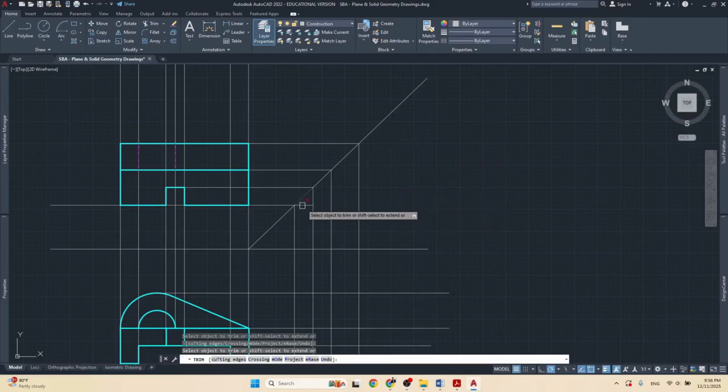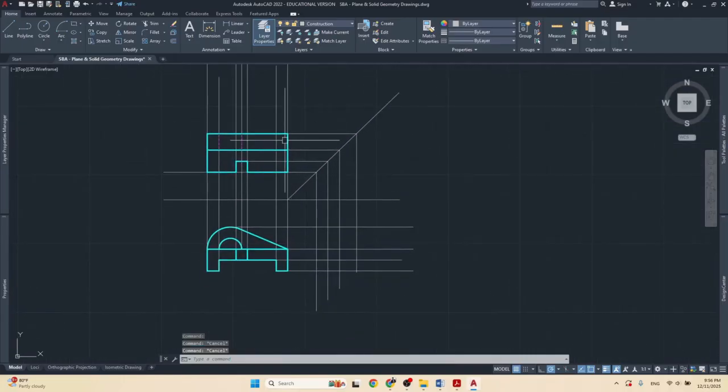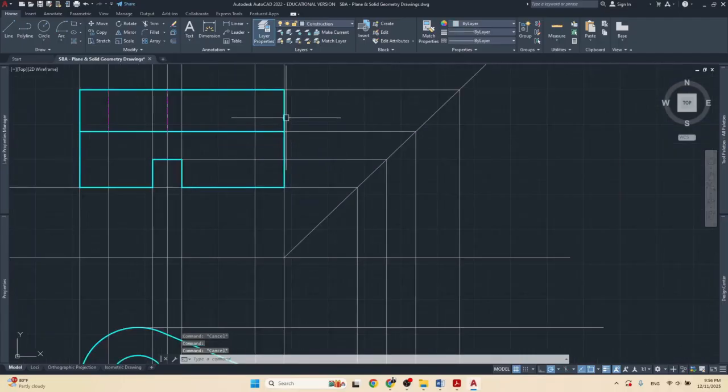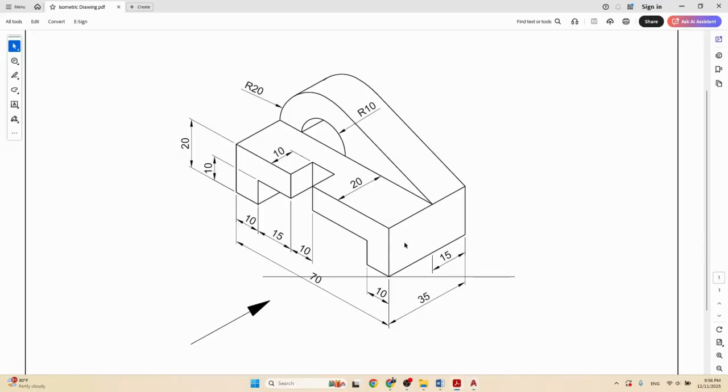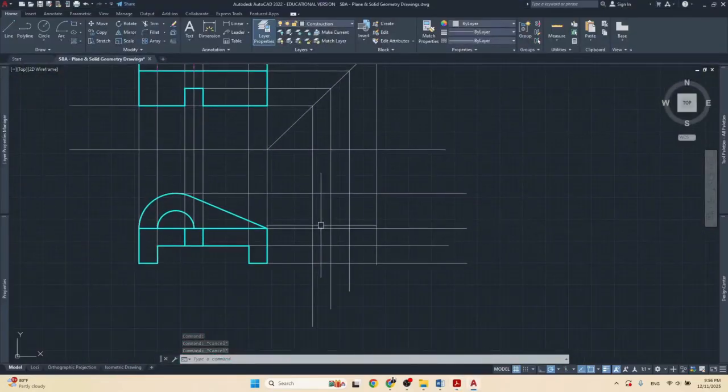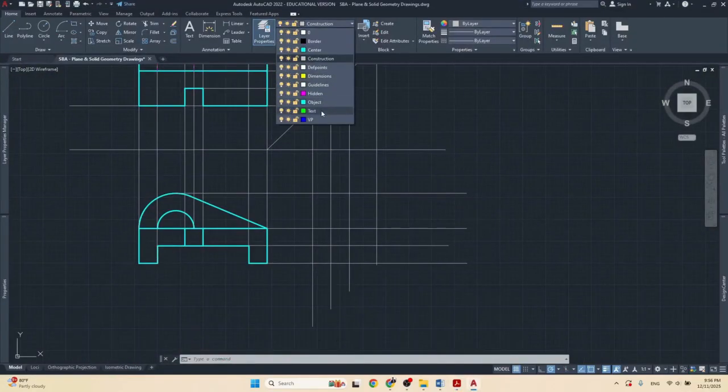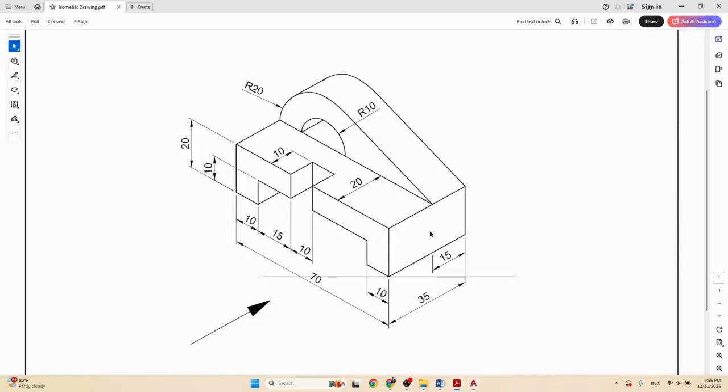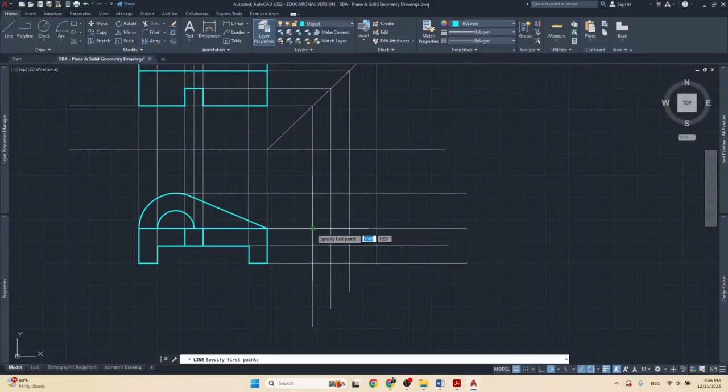Alright, so these lines come across and then they turn down at the 45-degree line. Once they hit the 45-degree line, they turn down. So I'm going to be drawing this face, this side of the drawing, which is over here. You should already know what it's going to look like. As I said, it's going to look like a rectangle, right? And because we projected lines, we don't need to measure anything. We just have to follow